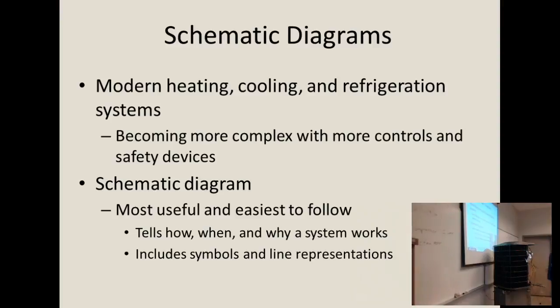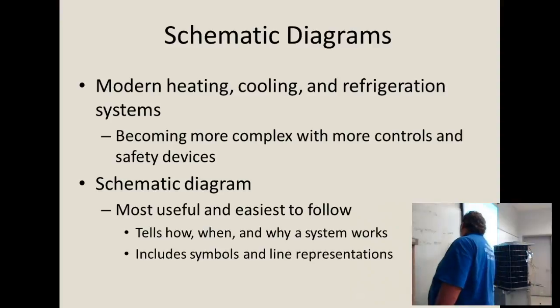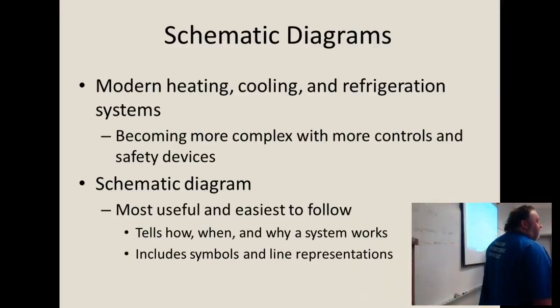How would you classify a condenser fan motor electrically? Path, load, source, or a switch? Load. What kind of load? There are 3 types of loads: capacitive, resistive, and inductive, right? And a motor works off a magnet, which means inductive.